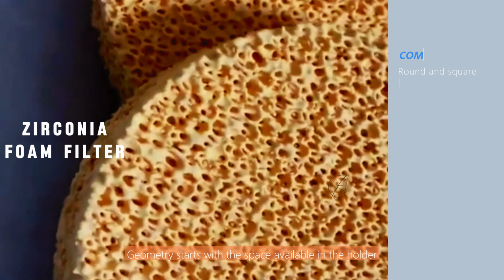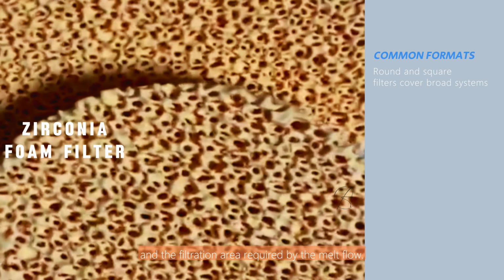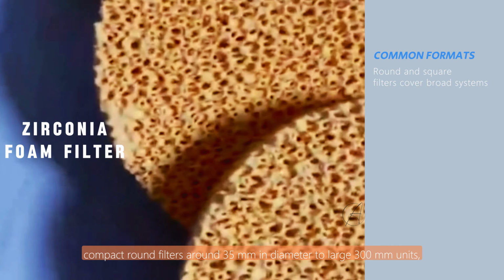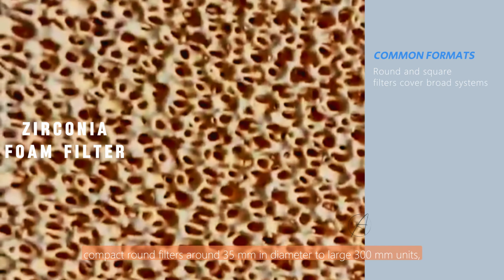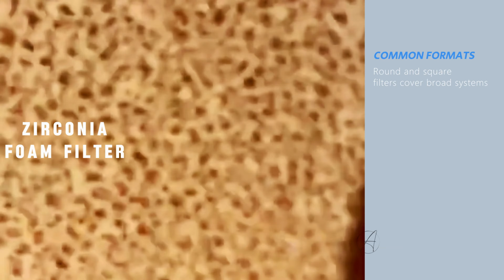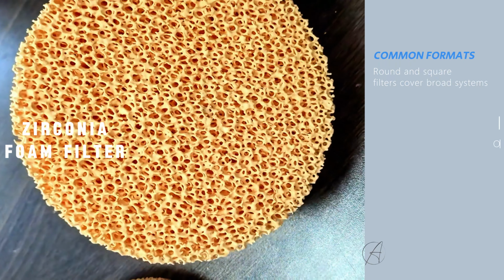Geometry starts with the space available in the holder and the filtration area required by the melt flow. Common production formats extend from compact round filters around 35 mm in diameter to large 300 mm units, while square formats span from roughly 30 mm across to 300 mm. Thickness rises with size and required structural support.